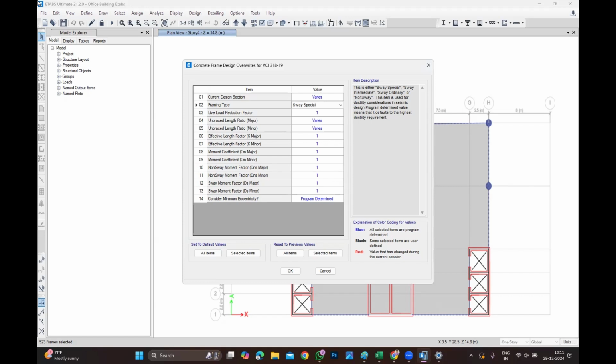Means what? People are on a new, fresh design, and with a lack of concept. Even if the design demands another 50 millimeters of concrete thickness, they don't want to do that. Instead they increase the reinforcement, because they don't bother about the cost of reinforcement. They don't have any idea that concrete is much cheaper than reinforcement.